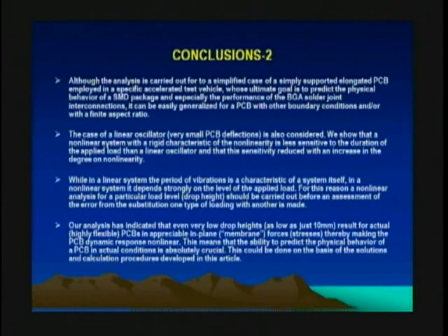And our analysis has indicated that even very low drop heights, as low as just 10 millimeters, resulted for an actual highly flexible printed circuit board in appreciable in-plane membrane forces, thereby making the printed circuit board dynamic response nonlinear. This means that the ability to predict the physical behavior of a printed circuit board in actual conditions is absolutely crucial. This could be done on the basis of the solutions and calculation procedure developed here.